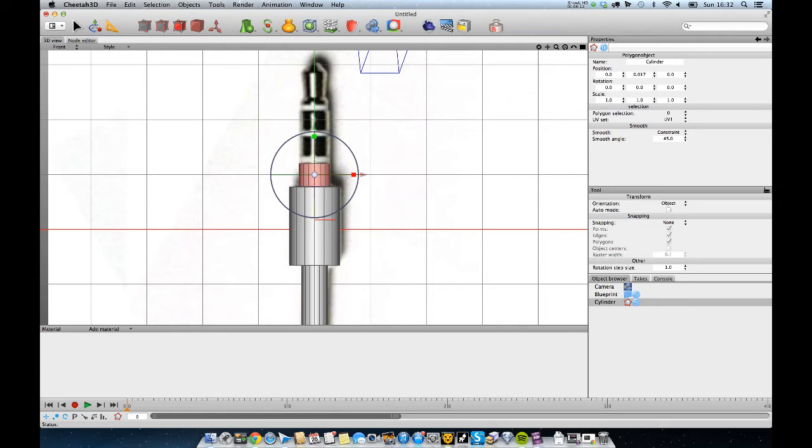Okay, so now we have this little white bit. I don't know the technical name for it, but it doesn't really matter. So I'm going to reduce that selection. I'll push Shift D back up to those top polygons. I'm going to cover, and I'm going to pull again. And I'm just going to block these out really quickly by pressing C, and then just moving, C, moving up again, C, up again, a couple more.